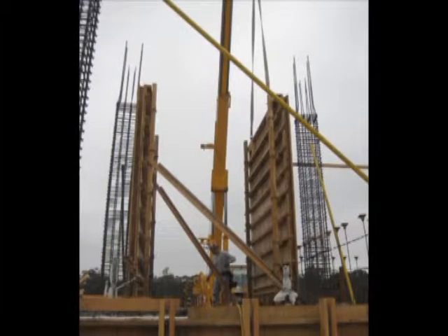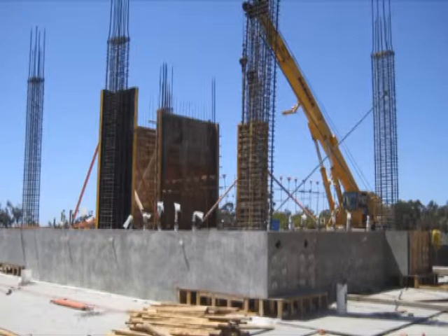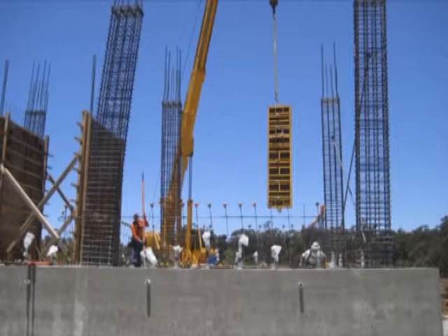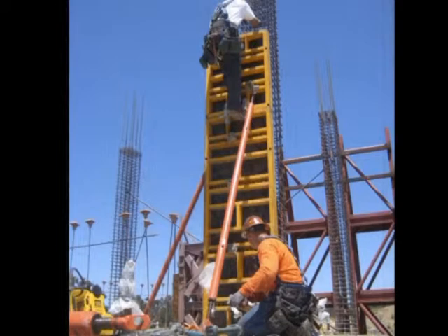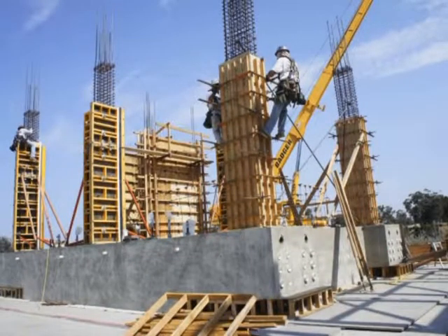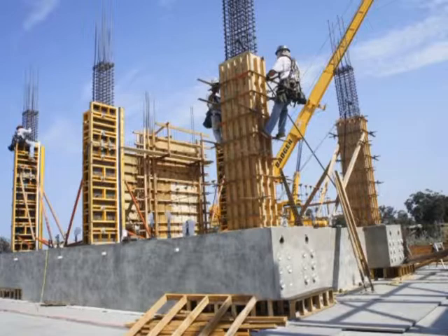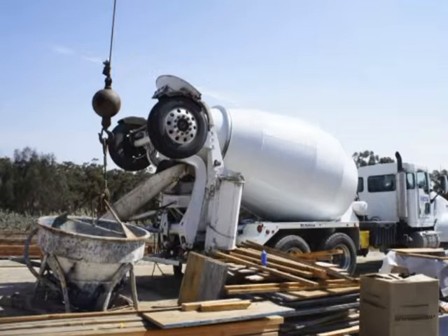Both sides of the shear wall require formwork to support the wet concrete, while the top of the formwork is left open to facilitate placement of concrete. The formwork for the 4 columns at the corners of this building is installed in a similar fashion. The shear walls in this building were designed with the same shape throughout the height of the building, aligned vertically, and supported on a deep concrete footing. This type of consistent configuration from floor to floor results in repeated use of the wall formwork, increasing construction efficiency. Once all formwork at a given floor level is secured, the structure was ready for pouring the concrete.